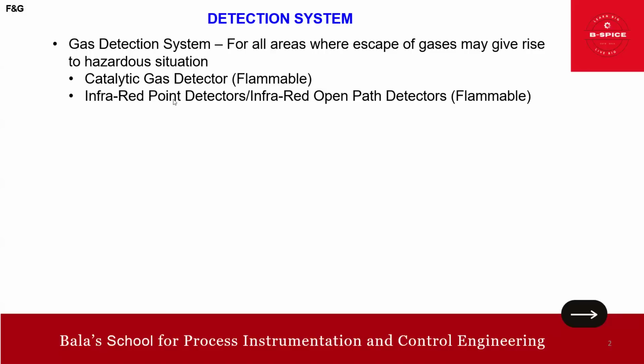As the name suggests, this is a point detector, with localized detection. They also offer fail-safe operation. They use two wavelengths, active and reference, to ensure fail-safe operation. As for application, it is commonly used in industrial environments like refineries and chemical plants to monitor gas leaks.